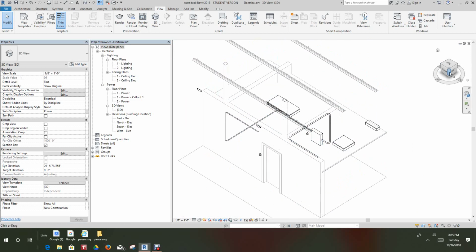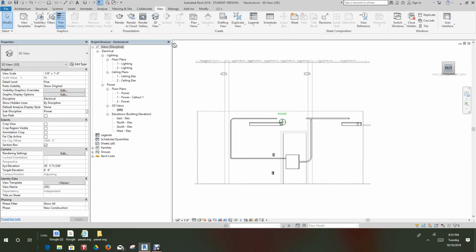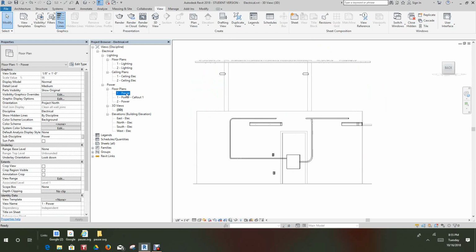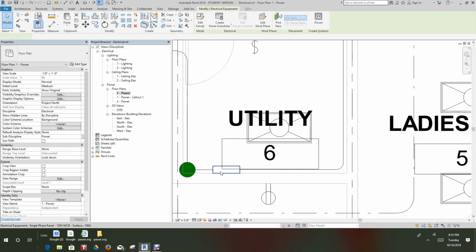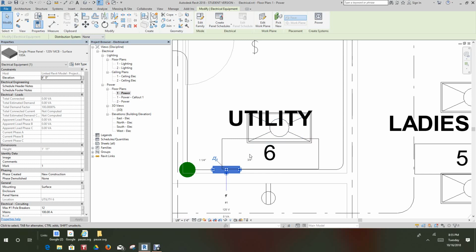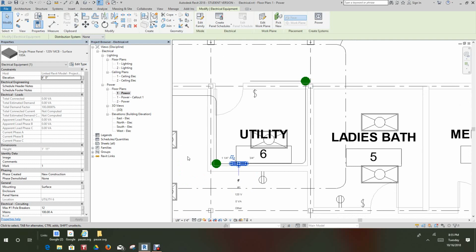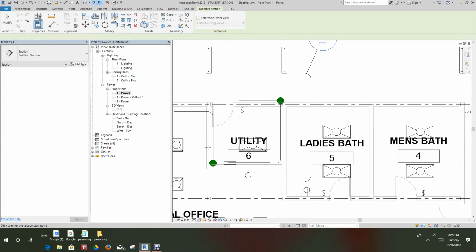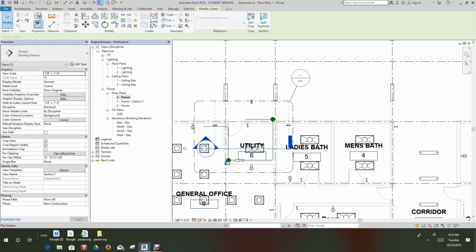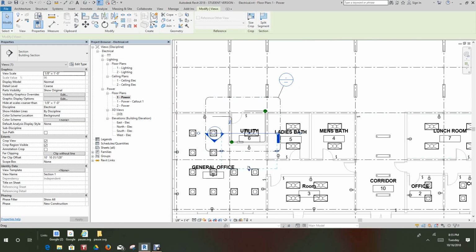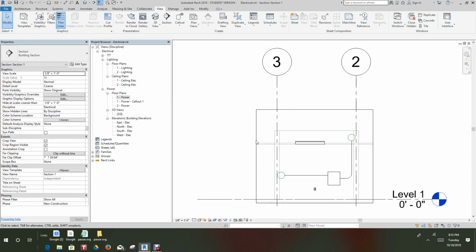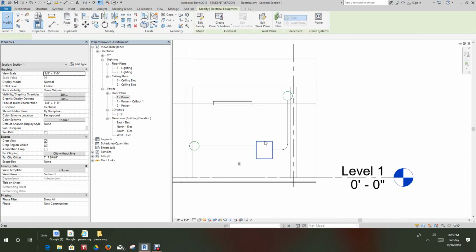So go to your electrical room, create several conduit runs. Okay, let's do another one right quick, just for the heck of it. Let's go to power again, select the conduit, the panel, right click. Now another thing we can do is, I always like to use section views. So we can cut a section this way, and let's flip this, and let's go to this view.